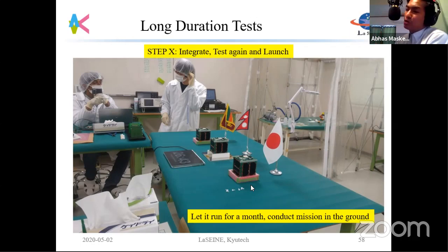That's based on the calculation, because you have 6 sides total, and 5 sides are solar panels, right? You have to see what's the worst case, because not all sides will be lit. Only 1 or 2 sides will be lit. In that case, what is the maximum power you can generate? What is the minimum power you can generate? And then you supply the minimum at that time. So you mean charging it with the minimum current that the satellite will get in the orbit, right? Yes, that's the point.